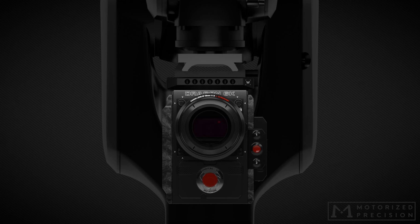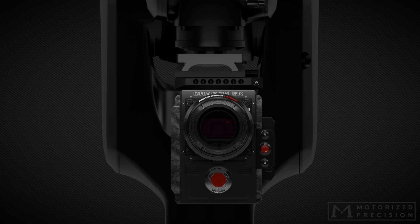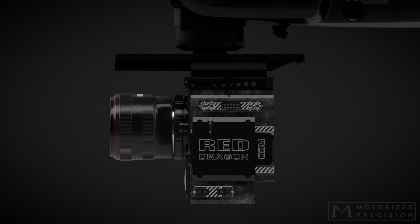Then we can measure the sideways distance from axis 6 to the sensor. We can take a similar approach here and look at the offset of our lens compared to the dovetail mount. Usually the holes on these mounts are placed in 10 mm increments, so frequently this can just be eyeballed. Finally, we can slide the camera forward or backward so that the witness mark is directly under axis 6. This would make our forward offset 0.